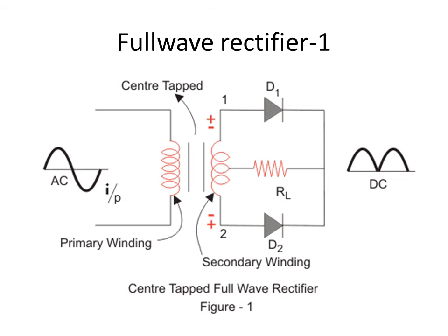So that is what is shown here. When you compare the input signal and the output signal during the positive cycle, this is how the output is varying, and during the negative cycle the current is flowing in the same direction as in the case of positive cycle through RL. So we have exactly similar halves at the outputs both during the positive cycle and negative cycle.